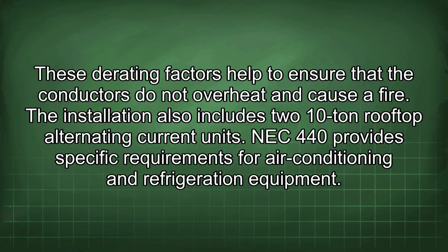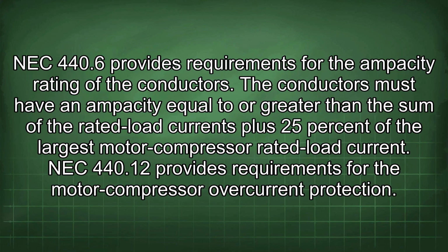The installation also includes 2 10-ton rooftop air conditioning units. NEC 440 provides specific requirements for air conditioning and refrigeration equipment. NEC 440.6 provides requirements for the ampacity rating of the conductors. The conductors must have an ampacity equal to or greater than the sum of the rated load currents plus 25% of the largest motor compressor rated load current.